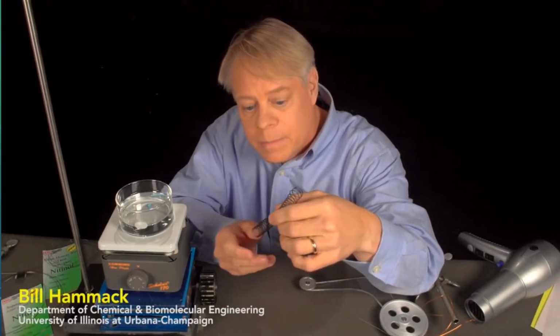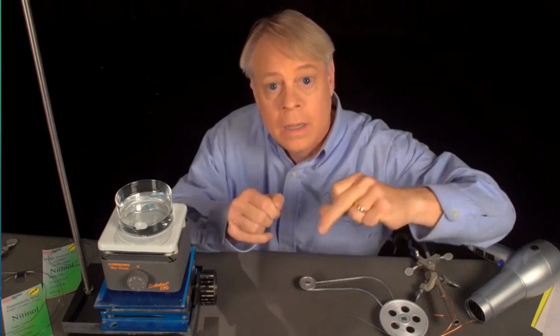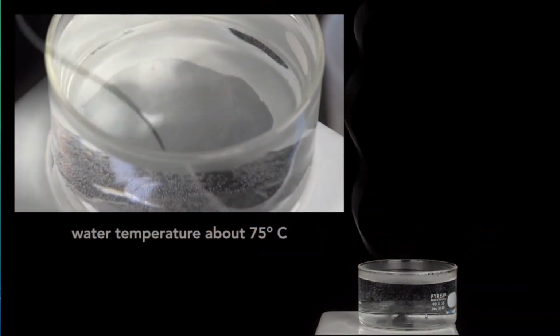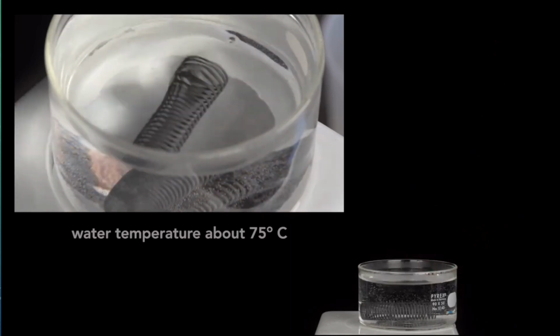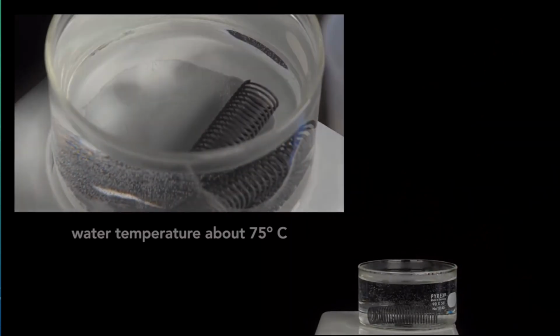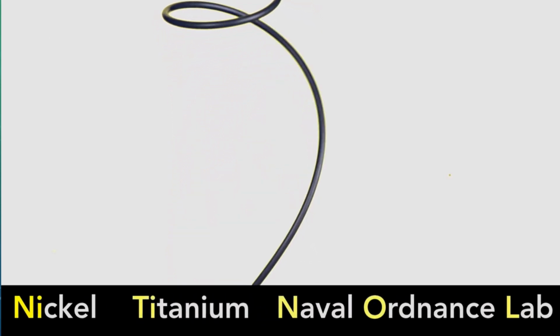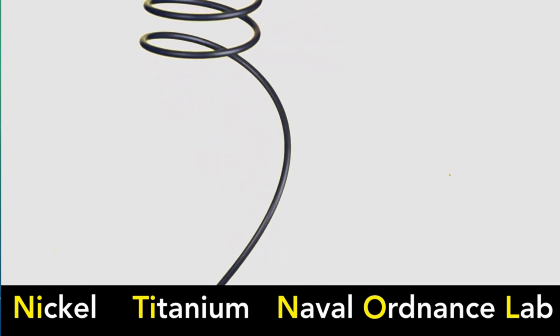This spring fascinates me. I'll completely uncoil it, except for a few kinks. Now, watch as I put it in hot water, 75 degrees or so. Rapidly, the spring reforms. Let's watch it again, but close up. Now, I stretch the spring, and then, to slow down the action, use a hairdryer to heat it. This spring is made from nitinol wire. The name comes from the elements it contains and where it was discovered: nickel and titanium at the Naval Ordnance Lab. It's showing what's called the shape memory effect.